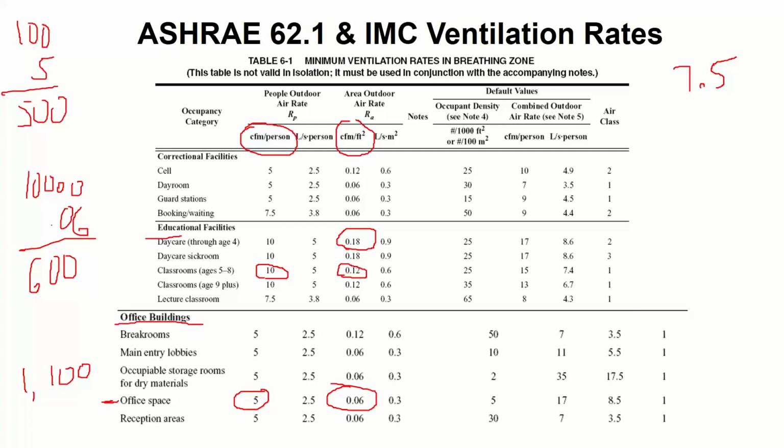Chicago does have a table like this, but it's not for ventilation air. It's actually for supply air, which is completely weird because, as most of you guys know, because you're engineers, the supply air CFM should be dictated by my load, not my square footage. I might have a square footage of a certain space that has single pane, crappy, leaky windows. I might have another one that's a super tight box. Should not be the same answer. But in Chicago, the amount of CFM you deliver to a space, supply CFM, is based on the square footage, not the load. And then the outdoor air fraction is 1/3 of that, which ends up being a very high amount of outside air. So Chicago is the most ventilated.